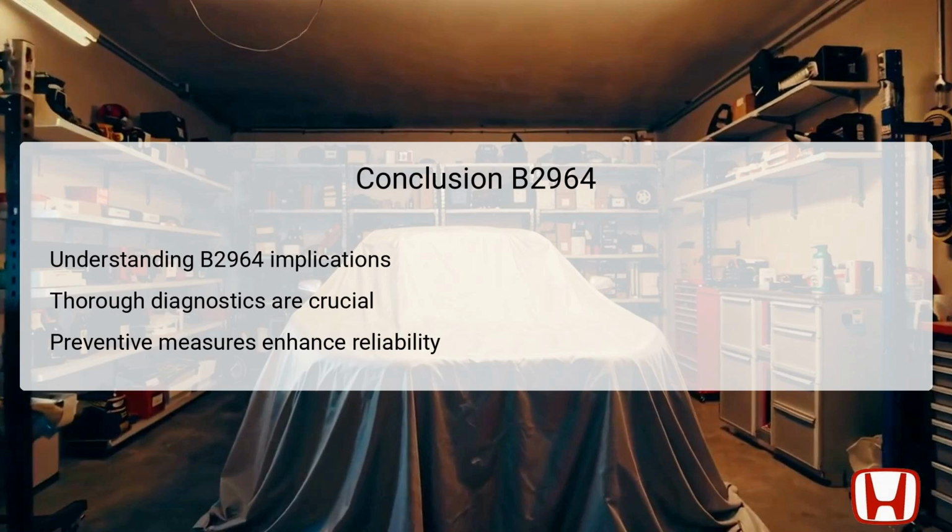A systematic approach to diagnostics, including verifying problems through existing codes, checking fuses, and evaluating wiring integrity, can lead to effective resolution of communication failures. Throughout the troubleshooting process, recognizing potential causes and symptoms is essential in targeting the repair efforts accurately. Implementing preventive measures, such as regularly checking connections and fuses, can enhance the reliability of the climate control system over time, preventing future occurrences of similar issues.